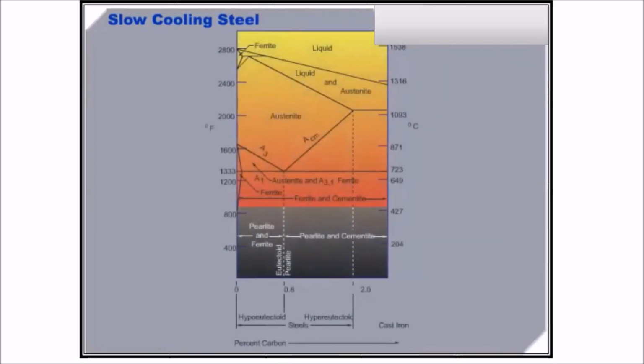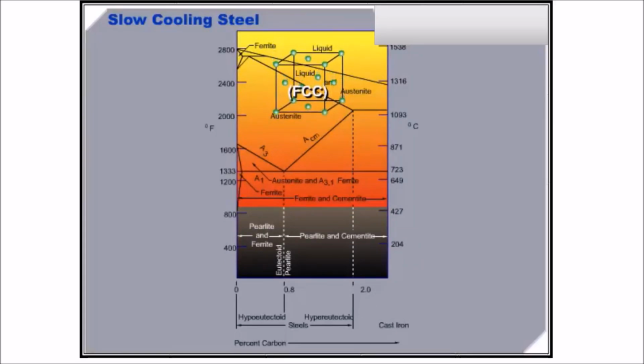Upon very slow cooling, these same changes will occur in reverse. It is the existence of this transformation that permits us to harden or soften steels through the use of various heat treatments. When a steel has been heated into the austenitic range and then allowed to cool slowly through this transformation range, the resulting microstructure will contain pearlite.